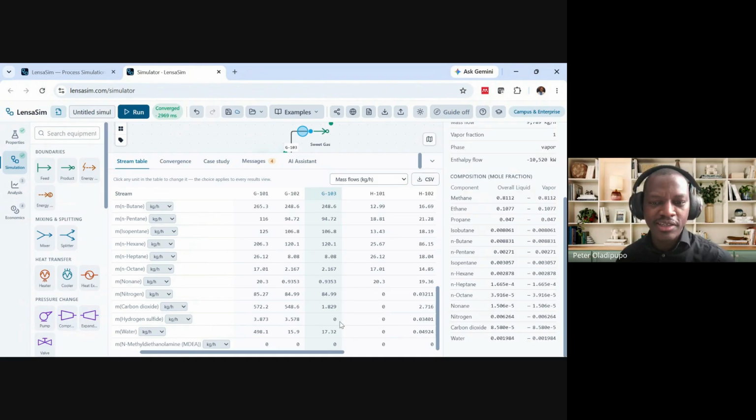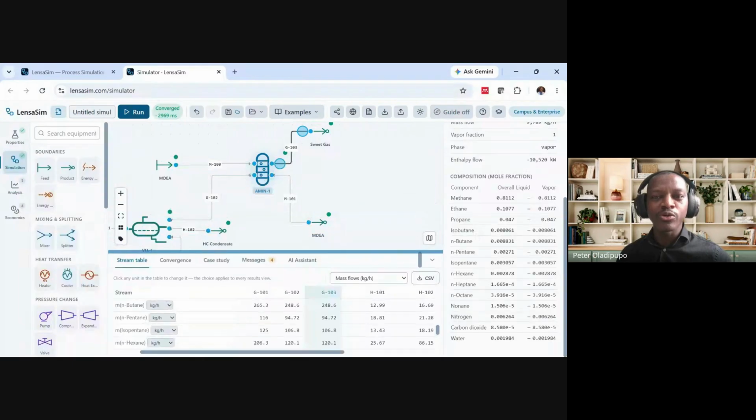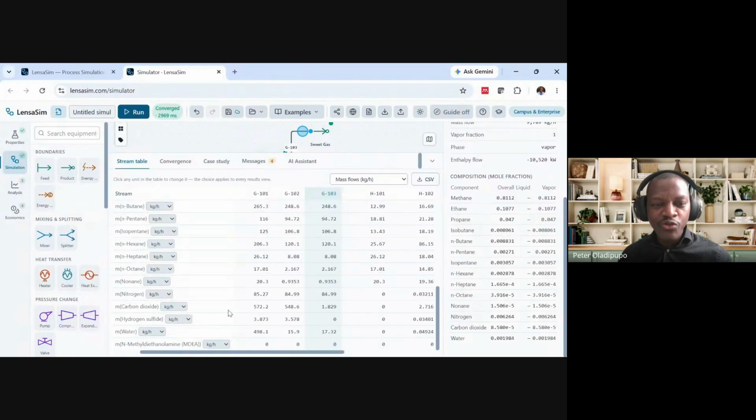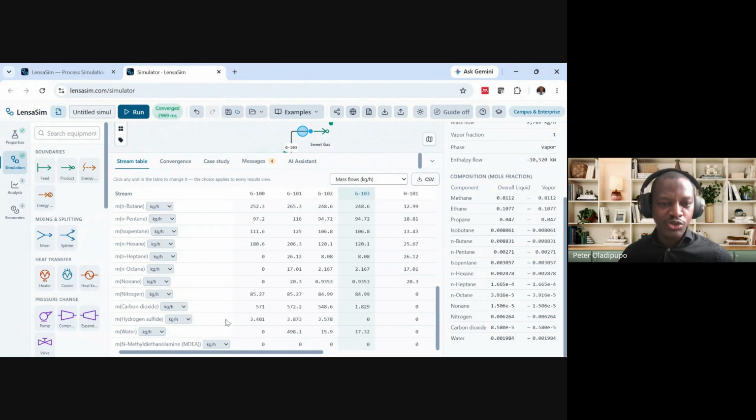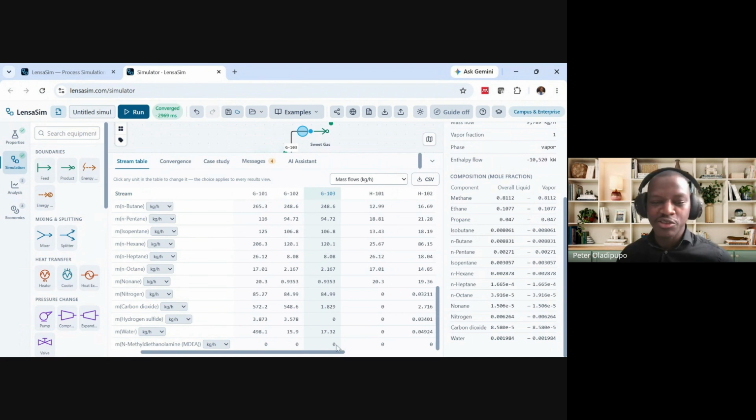It's now 0. So what you could see is that almost all the CO2 and all of the H2S has been removed completely from that stream. Over 99% separation is fine, so essentially we've achieved the purpose. The main sweetening unit has helped us remove the very dangerous CO2 and H2S contained in that stream, because if you don't remove them, they're going to cause massive problems for the plant, leading to loss of a $1 billion investment. So we don't want that to happen. So we've removed CO2 and H2S before we proceed with the processing.